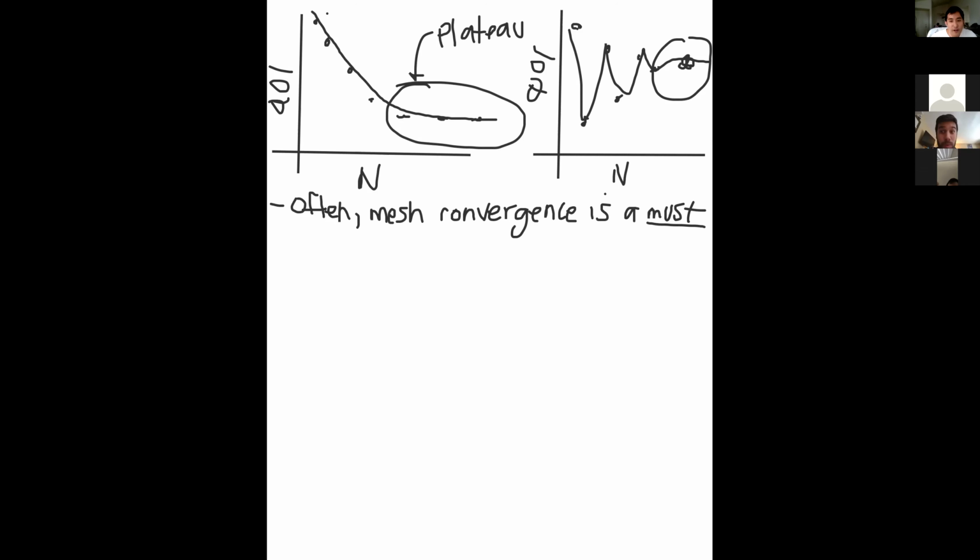So you can present your finite element results, but no one's going to believe you until you provide some proof and persuasion that what you did was legit. We'll talk more about this when we talk about V&V, which is verification and validation, after the spring break. But mesh convergence forms a very key component of this.